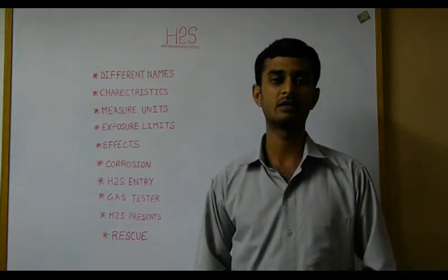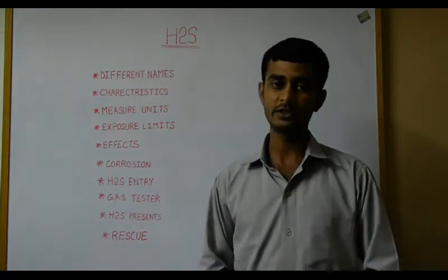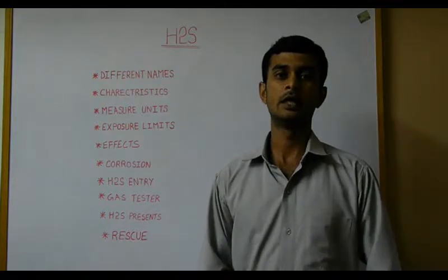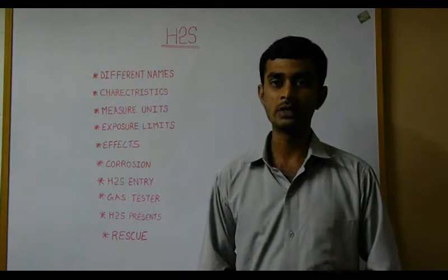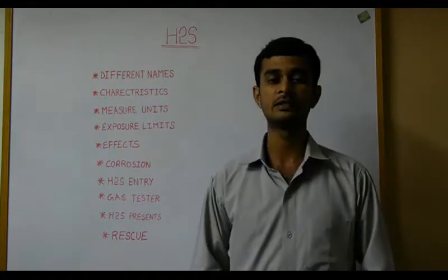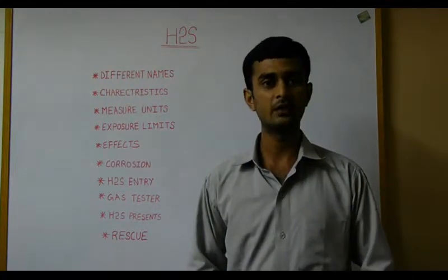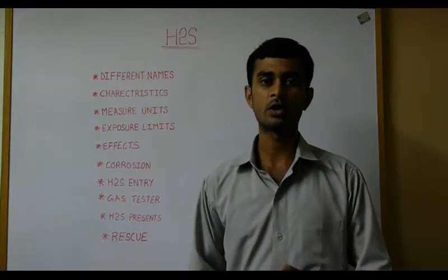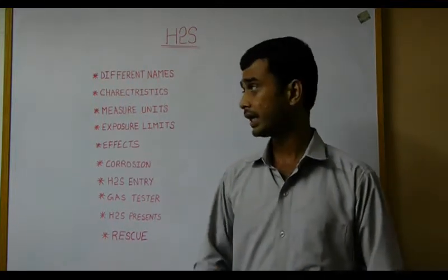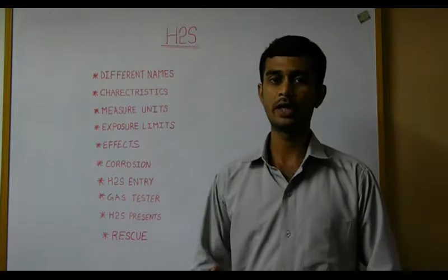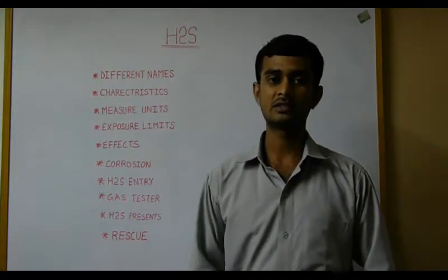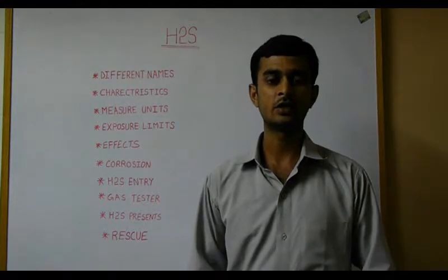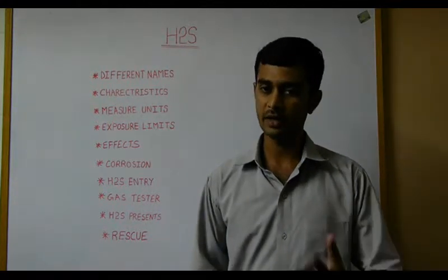Effects of hydrogen sulphide gas, as the concentration level increases. At lower concentration levels, from 0 to 10 ppm, hydrogen sulphide gas causes irritation to eyes, nose, throat and has a rotten smell. When the gas rises to 10 ppm and up to 50 ppm, this causes headache, dizziness, vomiting and breathing difficulties.